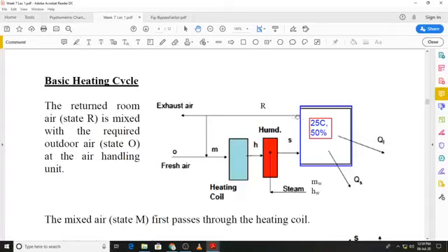Then that air which is in the room will be again returned or recirculated to the heating coil, and it is humidified, so that we have a constant cycle in which the heated and humidified air comes into the space, maintains it at the desired temperature, and when this heated and humidified air loses latent and sensible heat, it still maintains the desired conditions in the space.